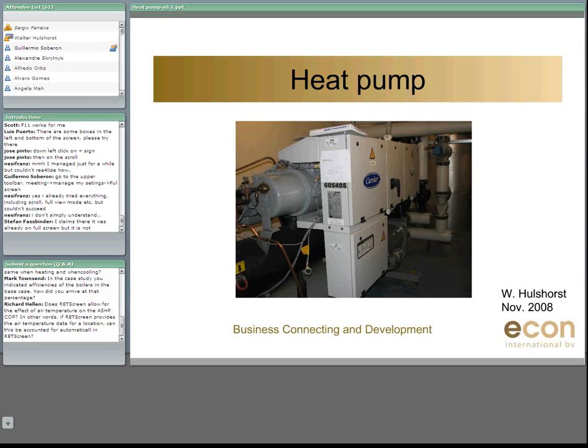I think, if you ask me honestly, more for the northern part, because with lake water you collect the heat which is provided during summer. You collect it and you want to use it within the winter. So it's more for the heating system, your lake water system. So I think for the northern part it makes more sense compared to the southern part where you already have good temperatures. So I think lake water systems make more sense for heating than for cooling mode.